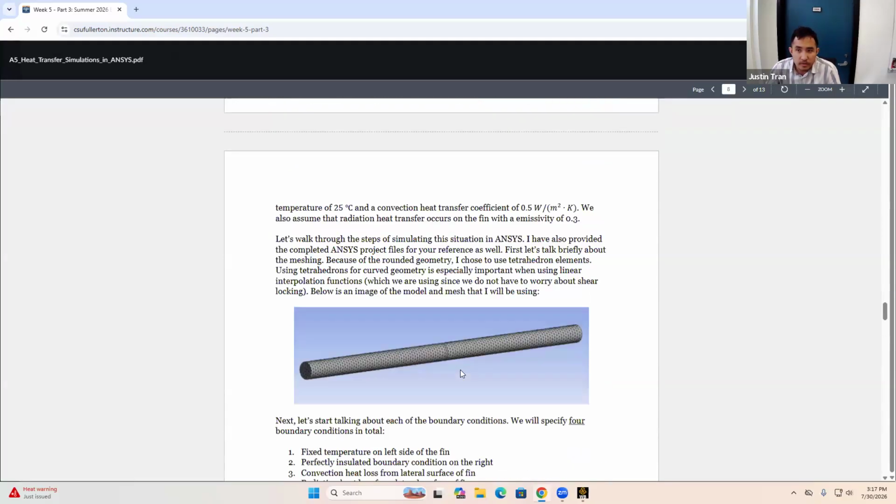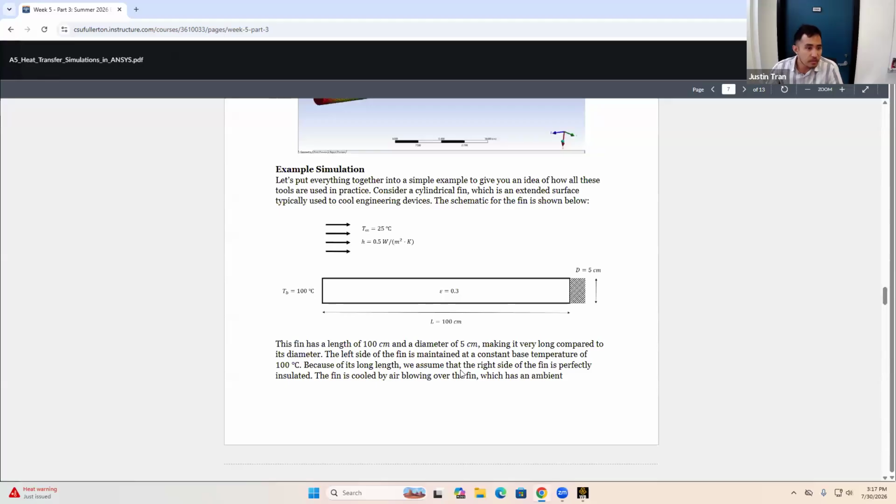Yes. I wanted to ask, this is not exactly related, but when we're working with, say, fatigue or static structural, and we do want to incorporate an operating temperature. There might be some flux, but it's minimal. But the idea is that the part you're simulating is really hot. Is that just a simple setting in ANSYS? So if the part is going to be at a constant temperature, you can specify that within just static structural.